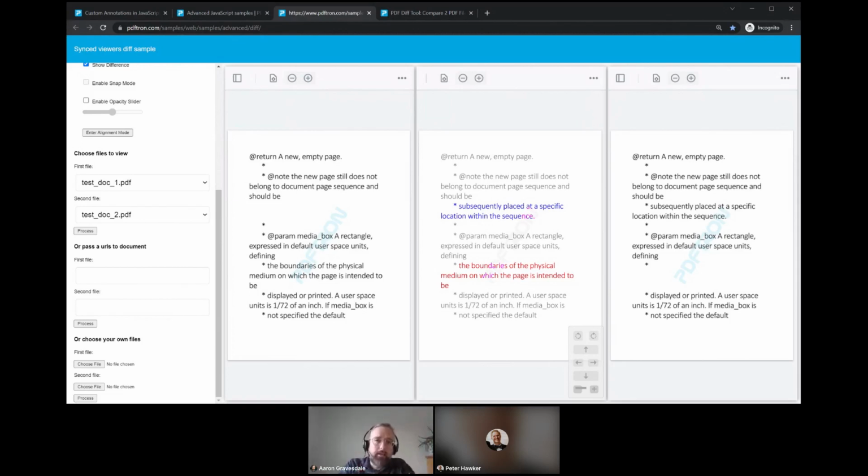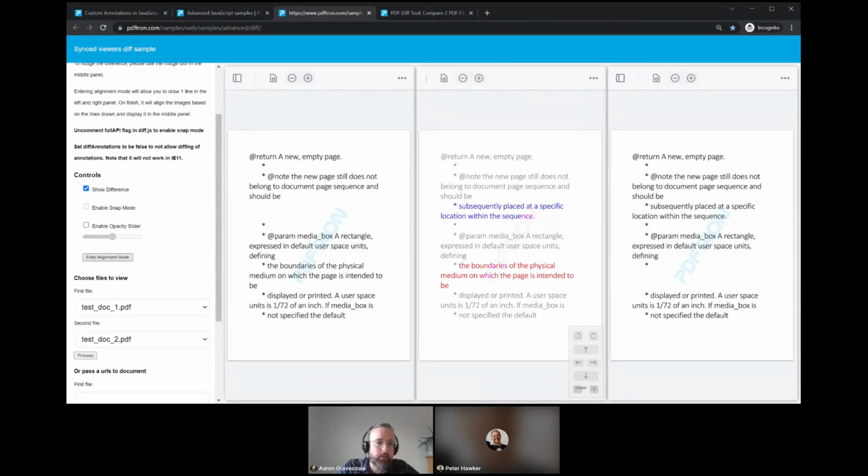And that way see if the house that we're planning to build will actually fit on the lot that we're building it on. So this is a good sanity check. You definitely want whatever you're building to actually fit in the place where you're planning to build it. And so we have some tools that are geared towards that. We call that alignment mode. And in alignment mode, what you can do is draw an arrow on each of these two blueprints.